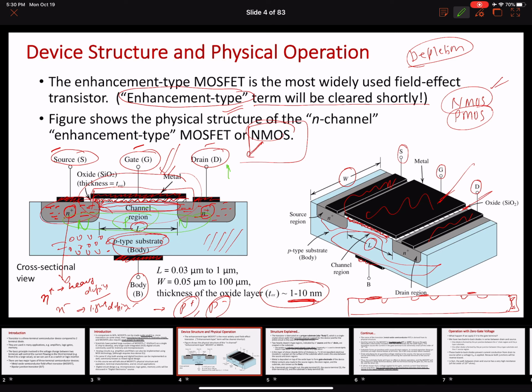So this is another important concept over here, because it helps us create the reverse bias conditions in an off condition, right? Reverse bias condition for both PN junctions, and this is important. For example, in a bigger substrate, if we have multiple transistors operating at different voltages, rather than connecting a body just to ground, we may want to connect the body to a negative power or negative voltage supply, the most negative one, just to make sure that all the transistors in this entire body are reverse biased.